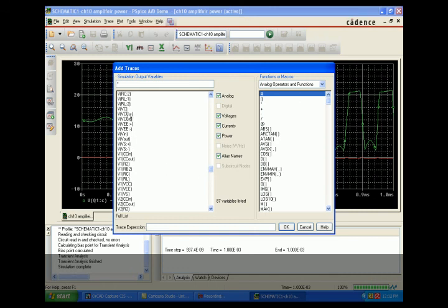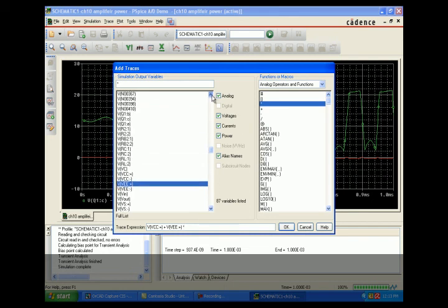Now we want to show the source power, so add a trace, the voltage at collector plus the emitter, and multiply with IC. So we want VCC, voltage at collector, VCC plus, we want to multiply plus with the voltage of the emitter, VEE plus. This could be the voltage as an input. We want to multiply that with the current flowing to the collector, IC Q1.